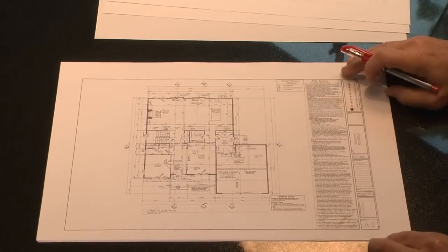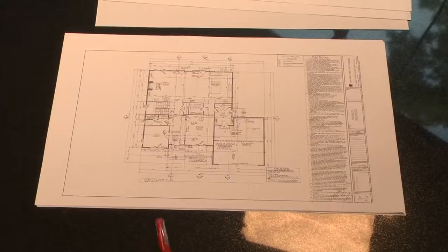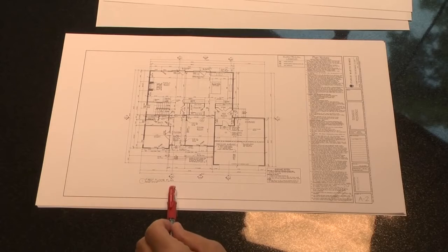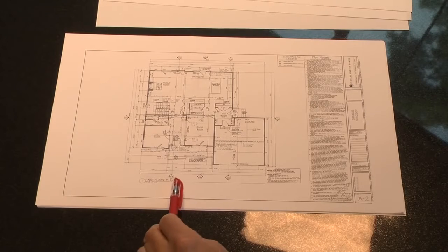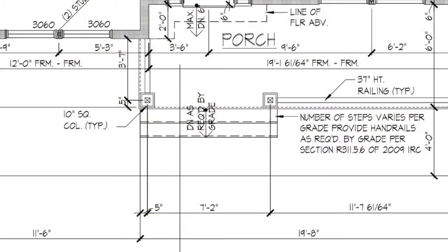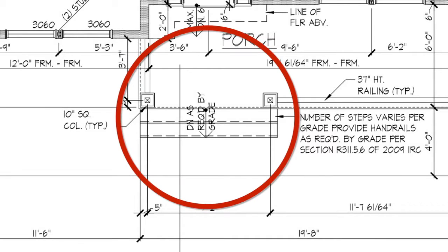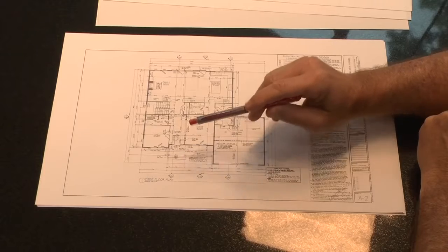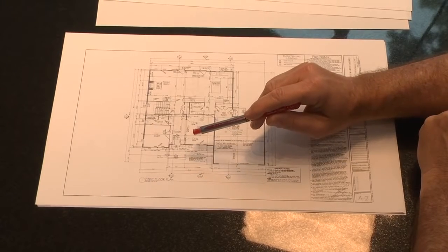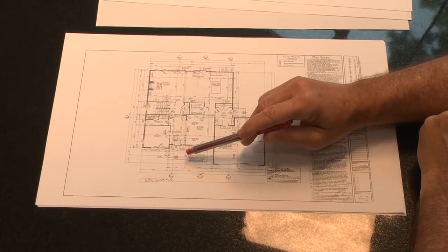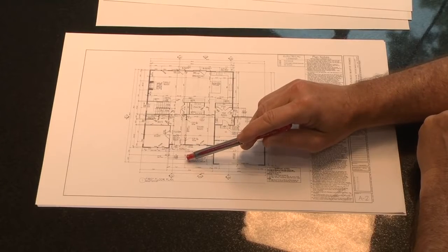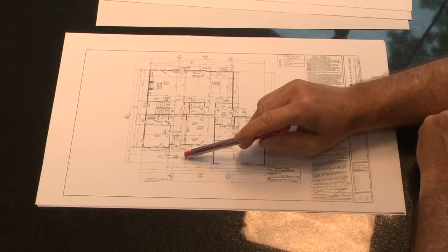So first floor, sheet A2. A couple things to think about. One is I like to start from reviewing the plans as if I were walking up to the house. In this case, you can see there are 2 physical steps leading to the porch. When you get your design set, we're not sure if there's going to be 2 steps, 3 steps, 5 steps. So the architectural plan is not trued up to the site plan yet. So we show prototypically 2 steps.